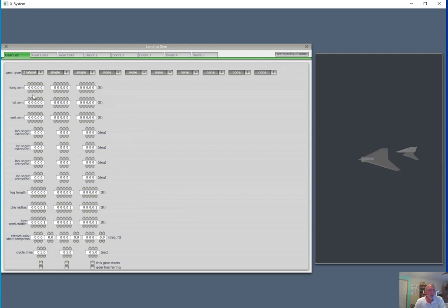So those are, there's going to be, this is the nose gear, so we're going to put that at -6.34. So that's forward of the datum, that's on the nose. And then we have a landing gear on each side on the wings.